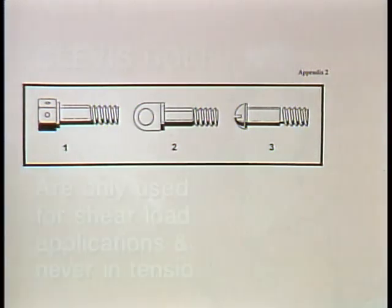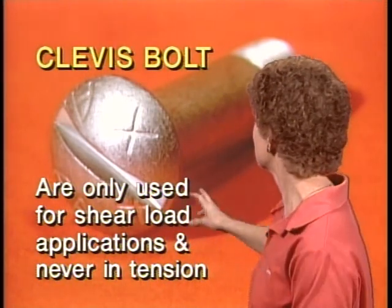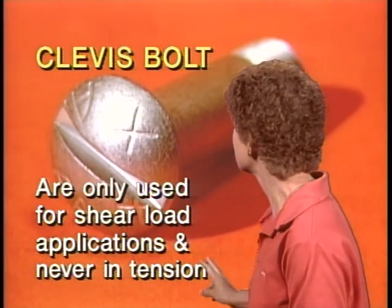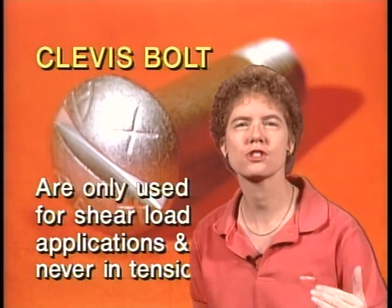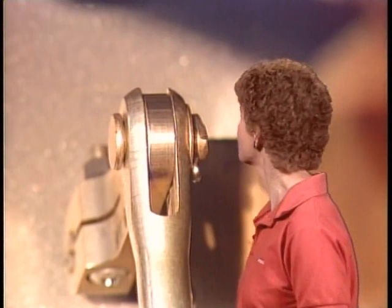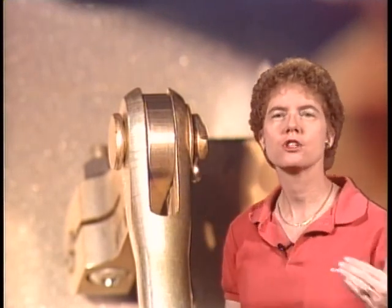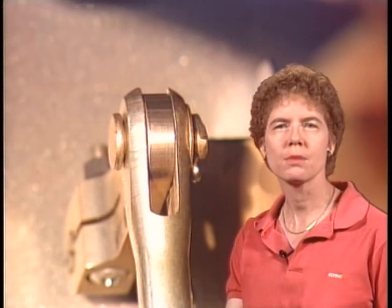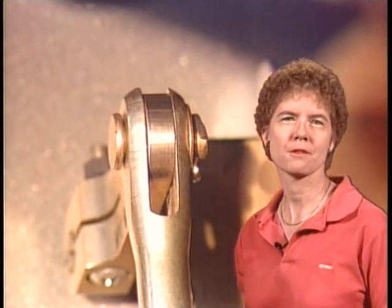Okay, talking about clevis bolts, how are they used? They're only used for shear load applications, and they are never used in tension applications. Never in tension applications, just for shear loads. Now, if you have a clevis bolt that's used with a fork end cable terminal, the way you secure it is with a shear nut tightened to a snug fit, but no strain imposed on the fork, and then you safety it with a cotter pin.